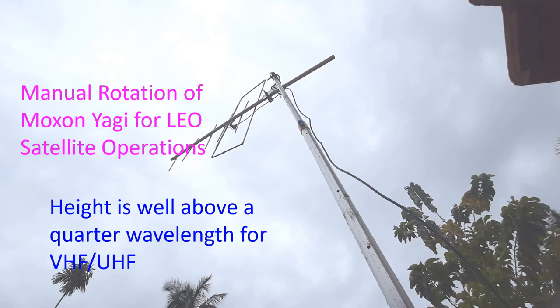Lower height in relation to wavelengths tends to direct electromagnetic waves towards the sky and is often considered wasted energy, except in case of NVIS, or near vertical incidence sky wave propagation, meant for medium distance contacts. Sometimes such antennas are called cloud burners in a lighter mood.